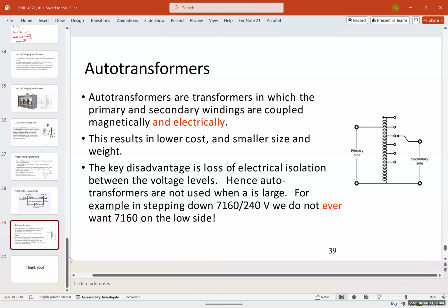One good example where these are being used is Japanese electrical devices. European devices usually run on 220 volts, and most Asian countries are 220 as well. But Japan and the US are 120 volts. So if you want to take your electrical device like a fridge and use it in Europe, an auto transformer is a good option because you can use it to increase the 120 volts, let's say, to 220 volts.